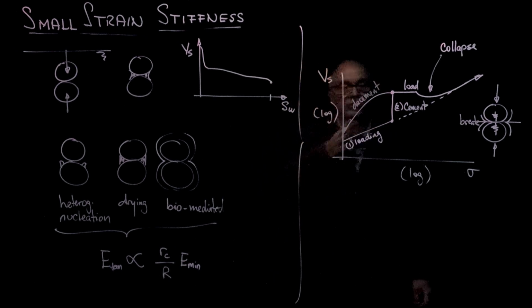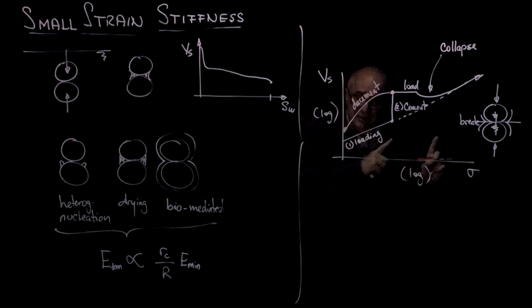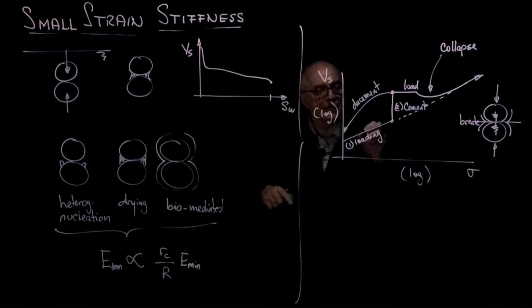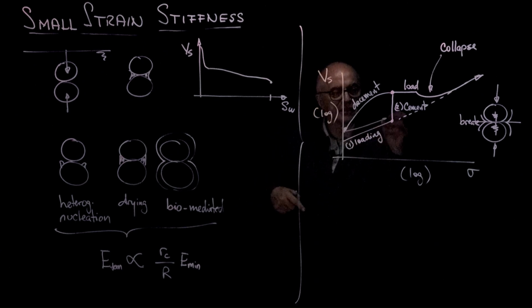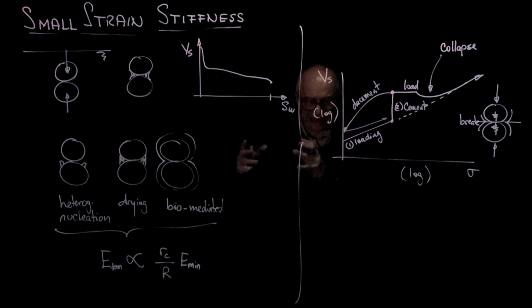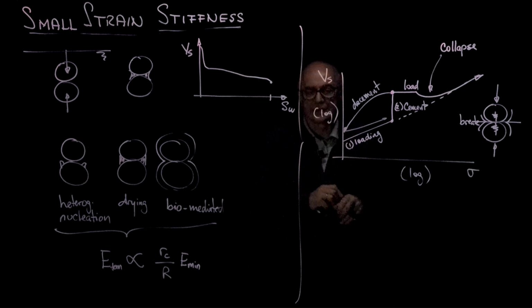And so during unloading, instead of unloading horizontally, actually it may experience decementation. And that is a situation where we sample these materials. Whenever we sample a material that has experienced some diagenetic cementation, even a rock, it does experience some degree of decementation. In soils, this can be quite critical. And then when we reload, we never get to see the original stiffness in situ, even if we put the specimen back into the state of stress in situ, that stiffness is lost.